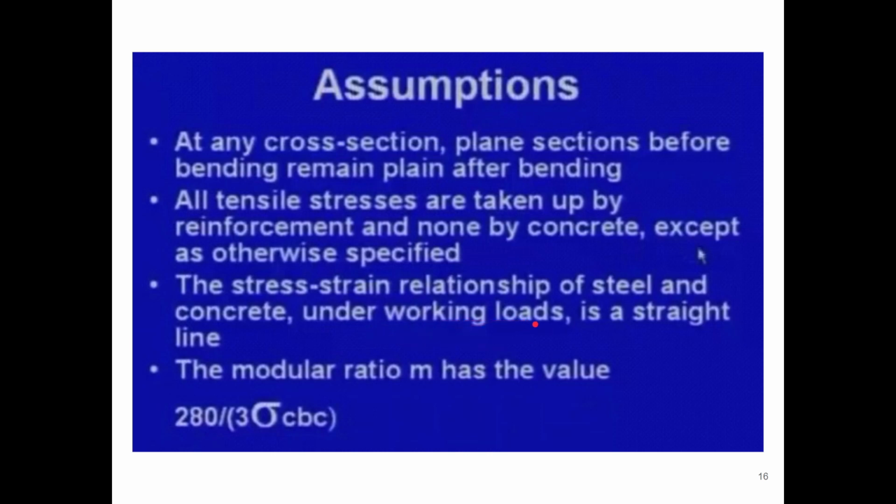Beyond the proportionality limit, where yielding occurs, we assume that the structure has failed, it has broken, it has been damaged. So we are not utilizing the non-linearity. That is one of the disadvantages also. This results in an uneconomical section. But we have less confidence in the design, so the working stress method basically only takes the permissible load or the working load.